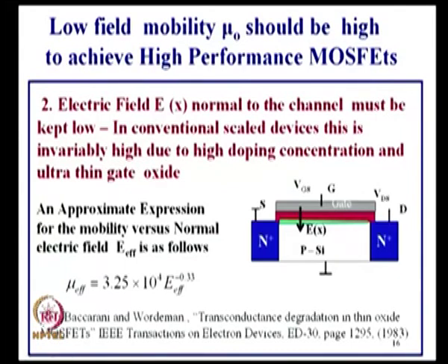The germanium atomic size is bigger than that of silicon. So, in these regions you have silicon and germanium atoms at the source end and the drain end. If you introduce that, the volume increases, because the radius of the germanium atom is bigger. So, in the given volume you are trying to introduce dopants which are bigger, so it tries to compress. I am sitting here, two fat fellows sit on both my sides, they will be compressing me. So, that is what is happening. You have germanium atoms added onto the source, that will be compressing the channel.